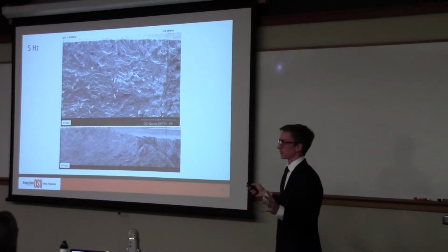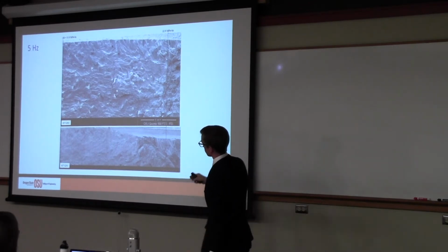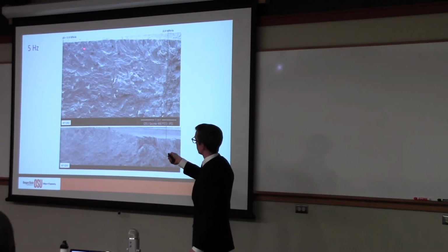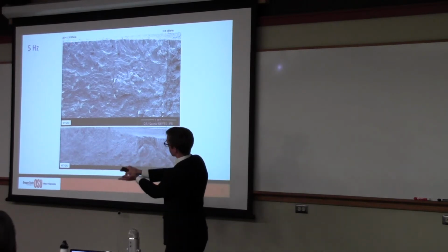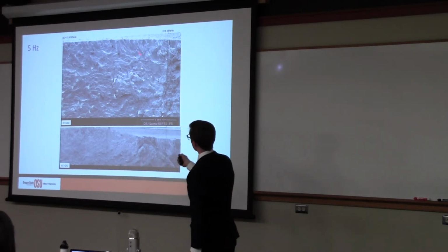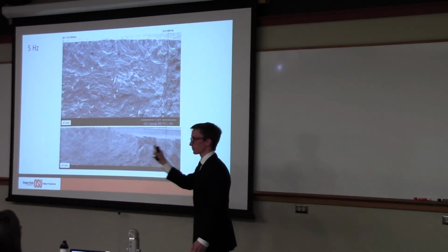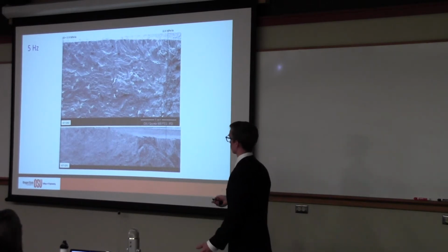Finally, some pictures. Let's look at these things. These are the fracture surfaces, and I should clarify. Up at the top, we've got the delta K experienced by the sample. These are increasing delta K tests. So the delta K experienced by the sample when the test first started is lower than when it ends. Okay? And the crack growth is happening from left to right on everything that we're looking at. That's the preferred orientation in the western world.